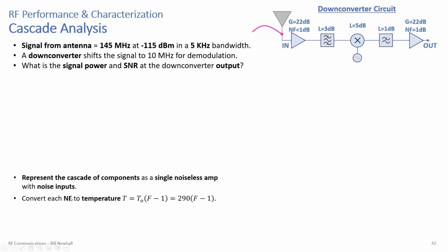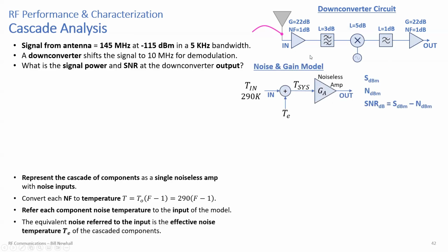Okay, so we're going to convert each noise figure to a temperature. We saw that conversion when we talked about noise figure. And then we're going to refer each component noise temperature to the input of the model. And this is the model. So we want to take this whole circuit and replace it with this equivalent.